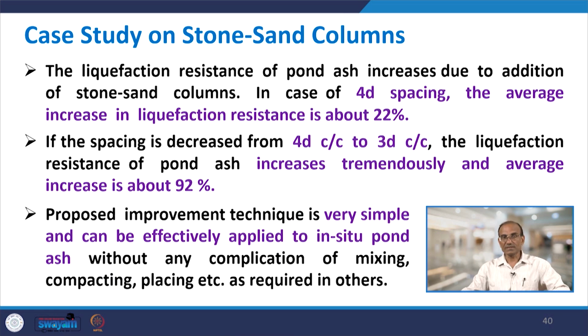So, what is the conclusion of this study? The liquefaction resistance of pond ash increases due to addition of stone sand columns. In case of 4D spacing, the average increase in liquefaction resistance was about 22%. If the spacing is decreased from 4D to 3D, the increase is tremendous and the average is about 92%, the effectiveness is 92%. The proposed improvement technique is very simple and can be effectively applied to the in situ pond ash without any complication of mixing, compacting, placing etc.